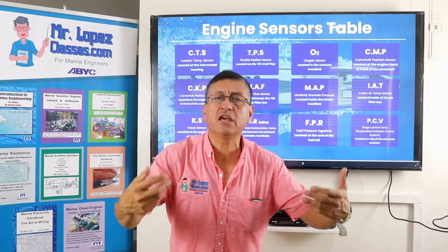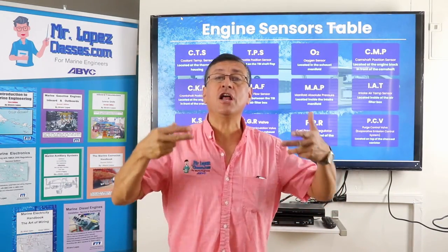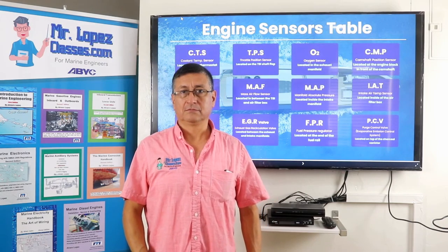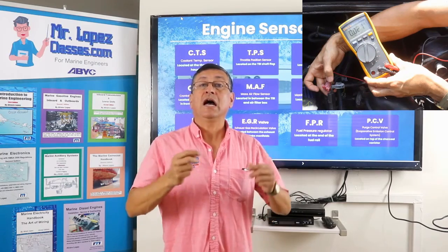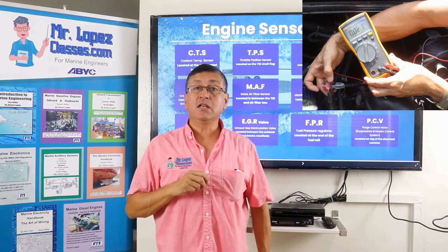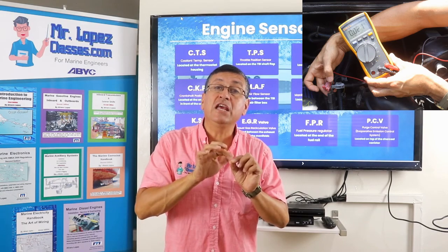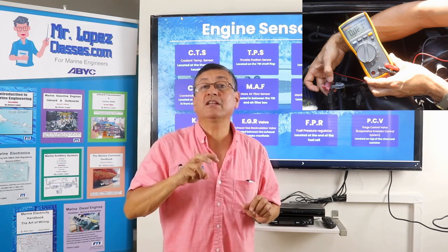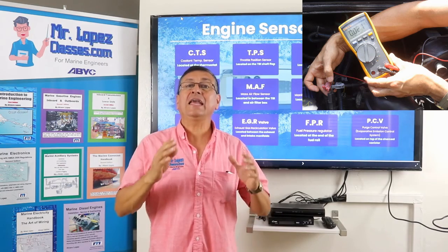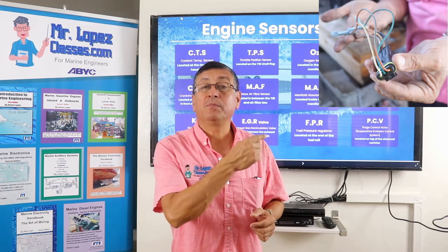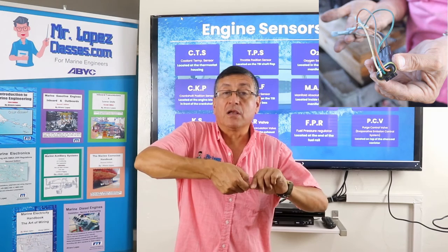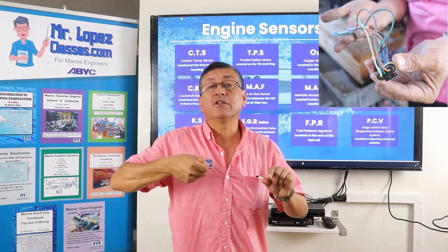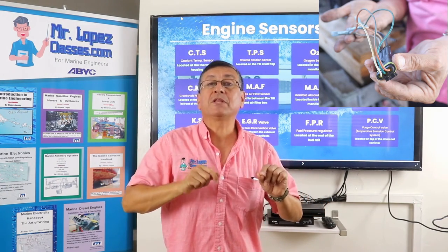And the majority of the sensors can be checked when the engine is running with voltage. In the same example, the throttle position sensor, I connect the plug, I start the engine, and I introduce needles in each cable to check the voltage. Or I can prepare tools like the tool that we are going to explain right now with Professor Rodriguez, in order to interrupt, remove the cable, remove the terminal from the sensor, and install the adapter.